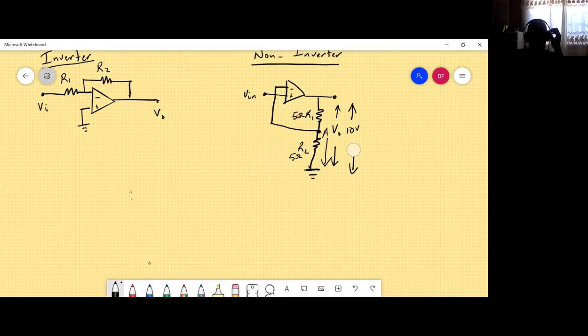So let us say for argument's sake now, we put 4 volts at this juncture here. Initially, this thing would be 0, and we turn on the switch and 4 volts goes into the non-inverting terminal. So the output is an amplifier, so the output starts to rise. Now it starts to rise, and let us hypothetically think it reached 2 volts. So the voltage across the output is 2 volts. What would be the voltage at the non-inverting terminal be?